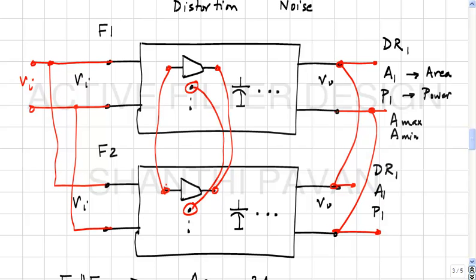In other words, wherever you had one transconductor in the original network, when you put two identical filters in parallel, every transconductance has become twice its value. What about every capacitance? Every capacitance has become twice its value. In general, every conductance and capacitance, or every admittance, has become twice its value. In other words, every impedance has become 1/2 its value.